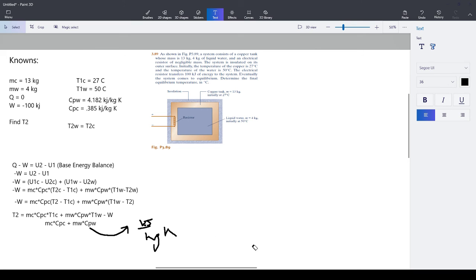So you do have to be careful that these are in the correct units. So temperatures have to go to Kelvin, but besides that, it all works out. But there is one last one here that is a pitfall for a lot of people. Right here is the work. So make sure we watch the sign here, because we have minus W, and remember, our work is already negative because it's work going in.